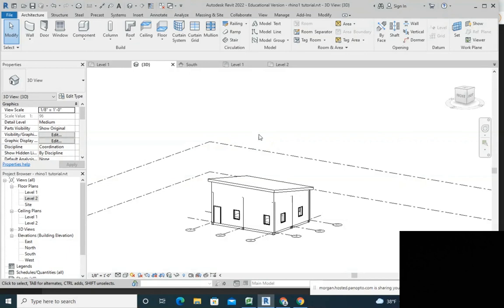Okay, and then select these 3. Hold shift, and I know you guys did this, you don't have to upload it, okay? Hold control, sorry. My bad, control. Uncheck define slope. This one, define slope, uncheck. And then select this line. And then, that's good, just hit check mark. Cancel for it right now. Okay. So attach. Okay, and then go to 3D. Over here. Yeah. Done. Okay, save. You're good.